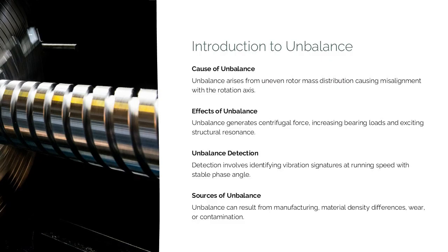Engineers must understand that unbalance can stem from manufacturing tolerances, material density variations, operational wear, or external contamination. Detection generally involves observing sinusoidal vibration signatures at 1 times running speed, typically accompanied by a stable phase angle. This foundational understanding sets the stage for deeper diagnostic investigations in subsequent slides.